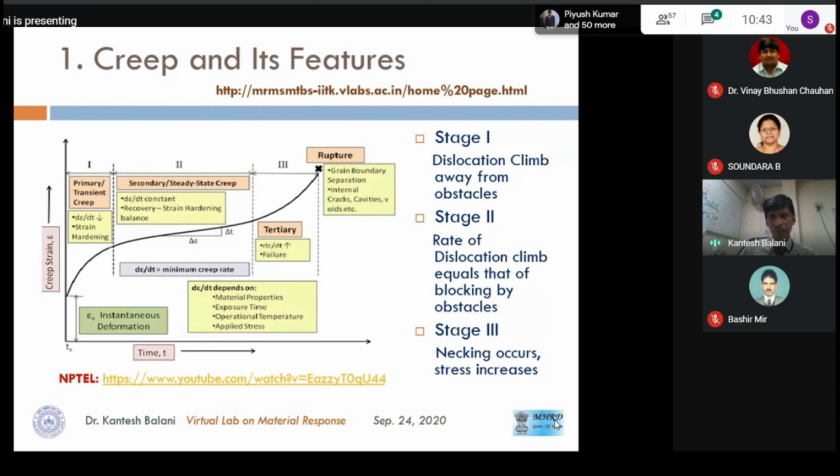So there are 3 different terms. It is time dependent, so with time the performance is changing. Plastic deformation is deforming plastically, and third part is high temperature. So high temperature may mean differently to each. Room temperature is actually high temperature for lead and tin, whereas even 1000 degrees centigrade is a low temperature for tungsten. So we need to also appreciate that part, how the material will change its response when it is being applied to high temperature as well as loading.